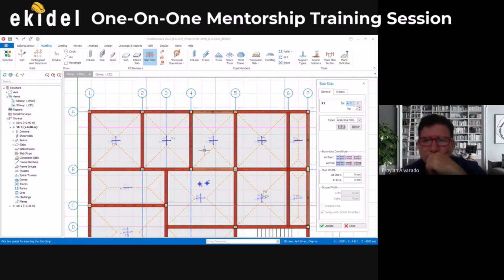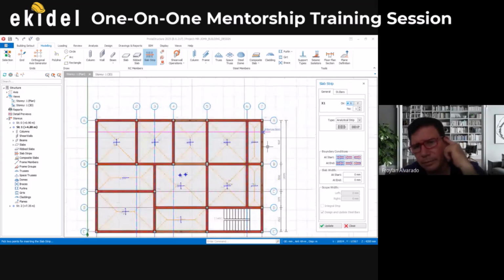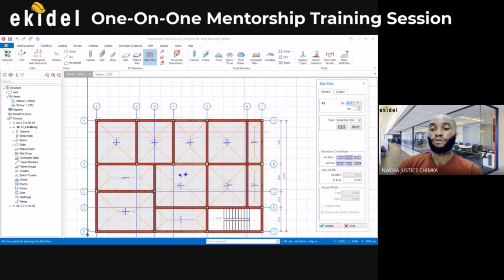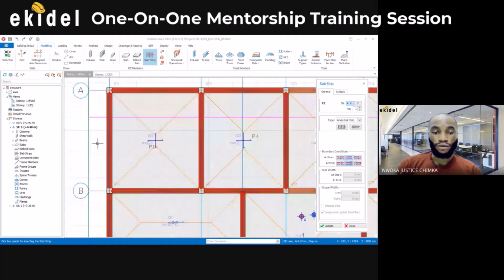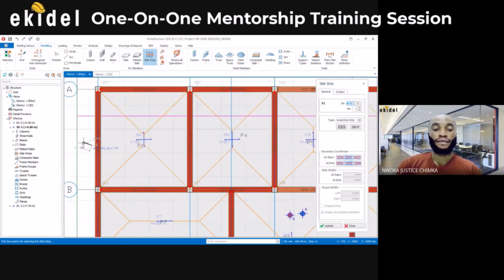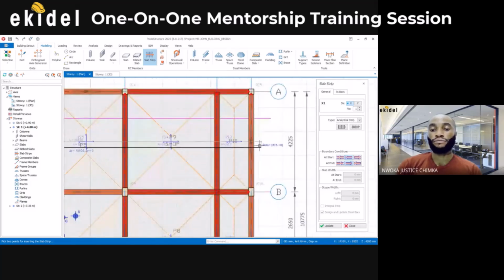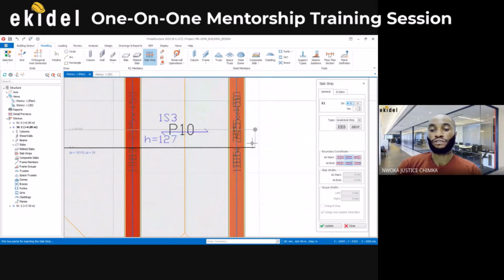So in this case now we have beam start and beam end. So I'll come here and click beam to beam end, and then I'm on the X direction. I'll then come, just take your hand after the beam, not too far. Then click, and then hold your control key to keep the line straight, and then cut through the panel, and again pass the beam a bit, and then click again.